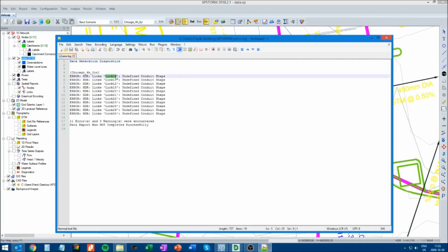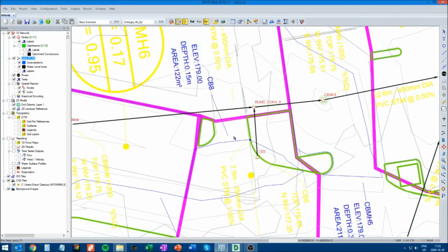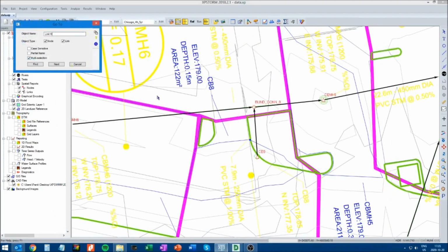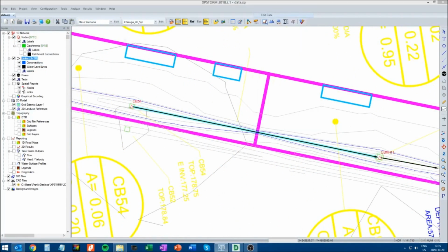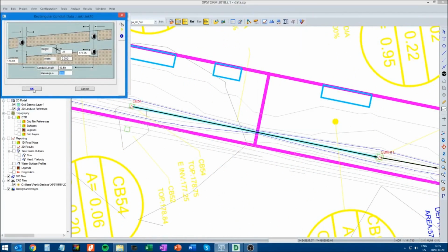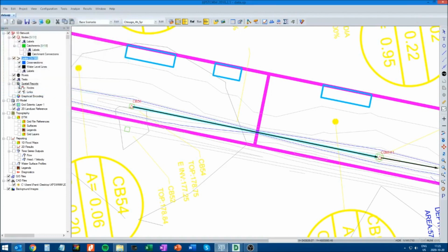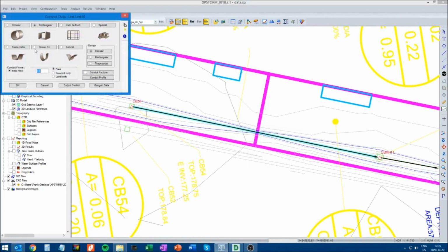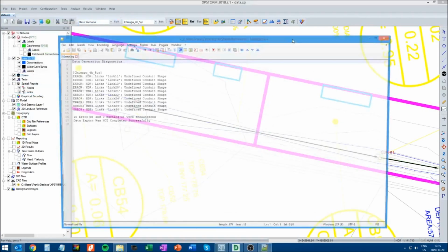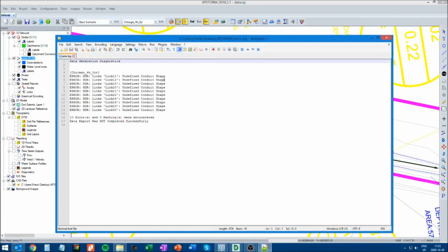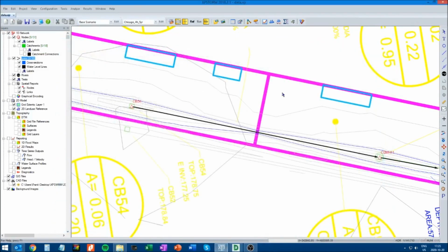Next one is link 10. So Control F, find link 10, edit, change it to rectangular, okay, okay, go back, change it to circular, okay, save, run it, and link 10 is gone from the error, so I think that solved it.